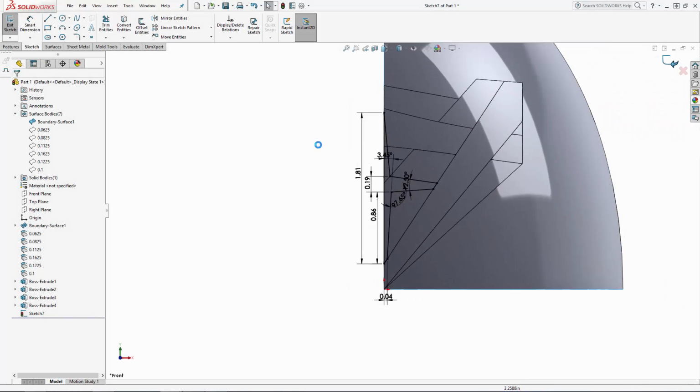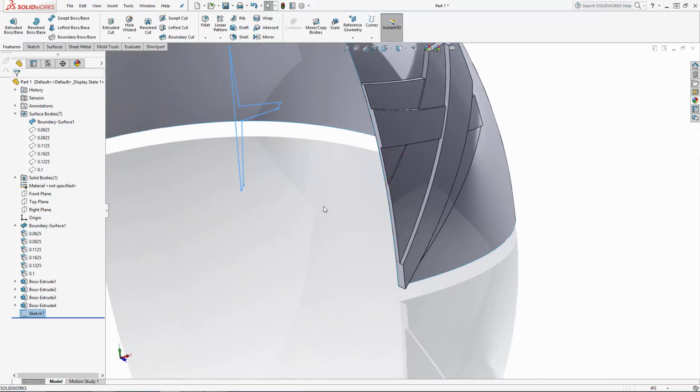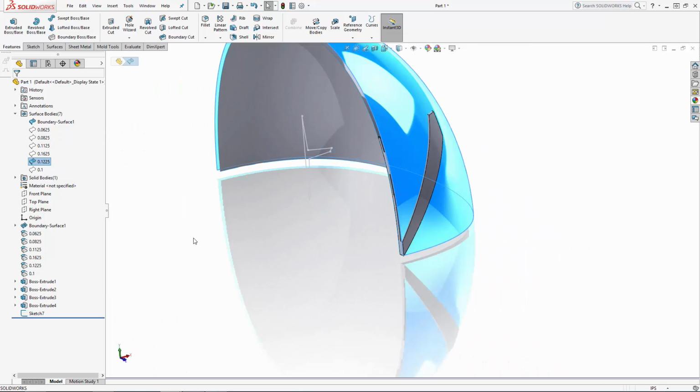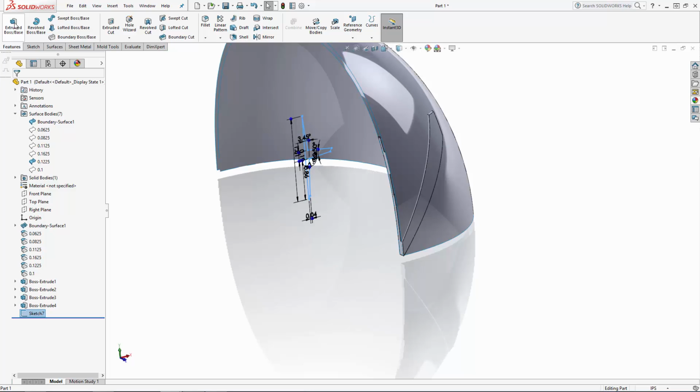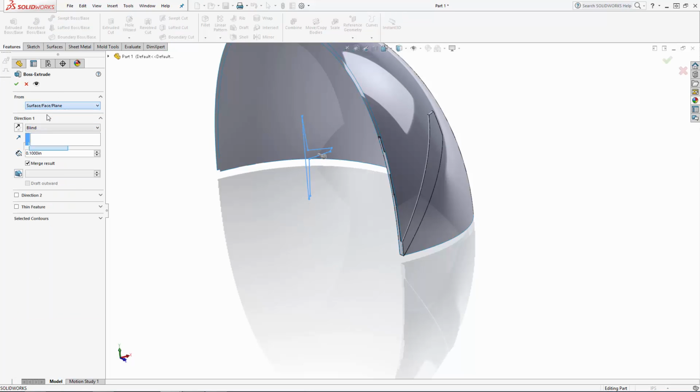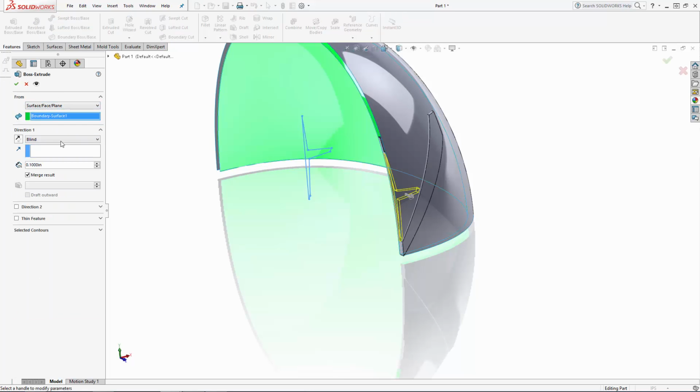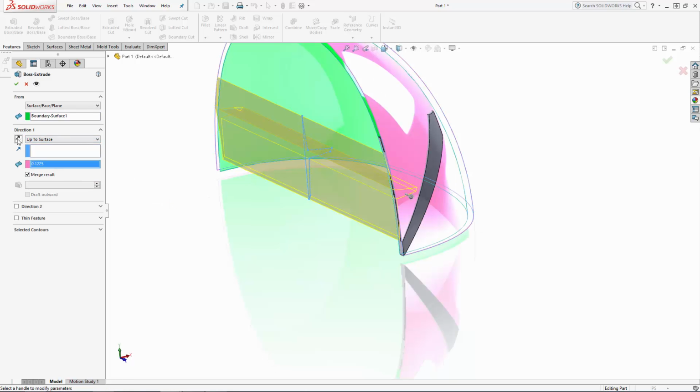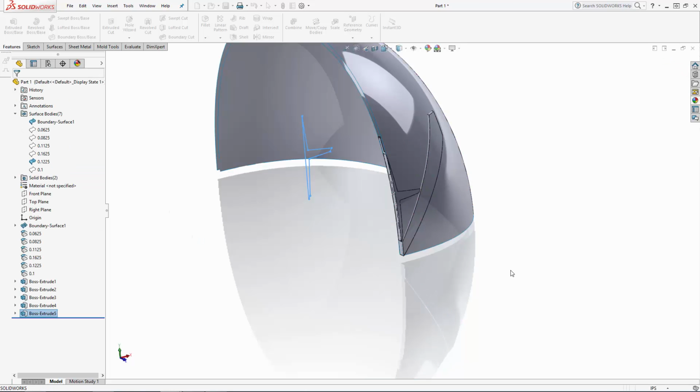So here I have the cross shape sketched out, and I'm ready to extrude to and from the appropriate reference surfaces, just as with the other extrusions. But after extruding this, I want to chamfer the tips of the cross a bit to create some separation between it and the other design elements. So I'm going to uncheck the Merge Result option to leave it as a separate body.